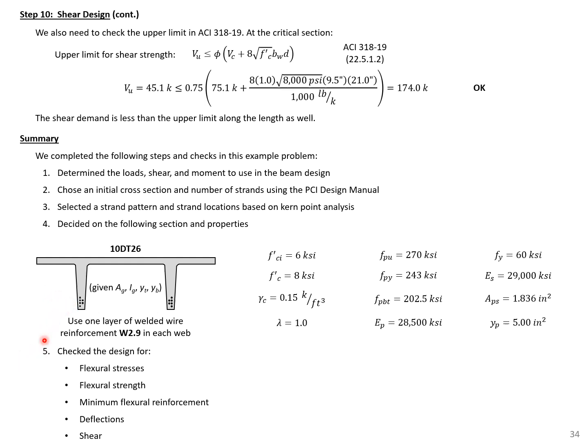And then we checked the flexural stresses, we checked our flexural strength, we checked the minimum flexural reinforcement requirements, we checked our deflections, and then finally we designed for shear and then checked our shear design. So that concludes this design example.